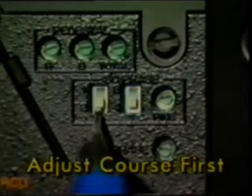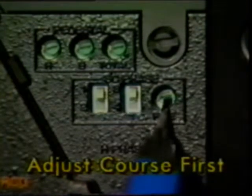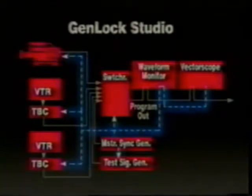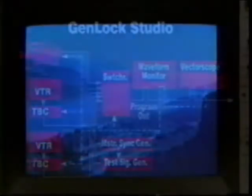Sometimes there are 2 phase adjustments. If so, adjust the coarse first, then the fine, to the precise burst alignment. When they are aligned, you've completed timing on video source 1. To time the whole studio, you would repeat this procedure with each piece of equipment. Having the equipment properly timed will ensure your input transitions are clean.